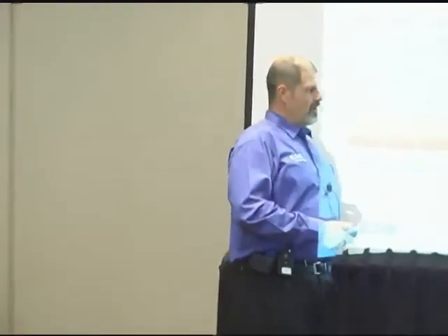So what we are doing now is every 4 months, in a planned, scheduled environment, we're actually turning off one of the modules. We're pulling it out of the circuit. So we start with module 3, we remove module 3. 4 months later, we're going to bring 3 back in, remove 2. The reason we're cycling them is for wear and tear and maintenance, and so they all get the proper recharge in batteries.